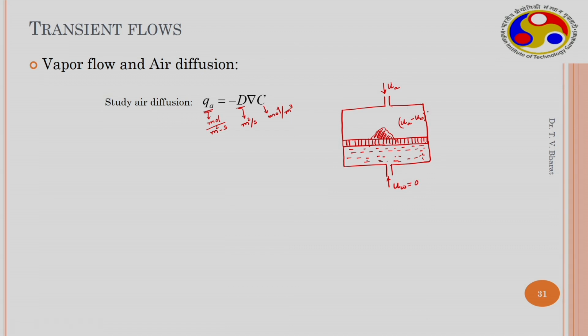pressure. So, in this particular case, if you have dissolved air in the water, so these are air pockets, some air pockets are available here. Generally this happens when you do not flush the high entry disc very often, and then some air pockets may be left over, available on the water side and sticking onto the high entry porous disc, as shown here. So, now when you are conducting a test at equilibrium, you have an air pressure that is maintained here and there is a water pressure that is maintained nearly close to 0.